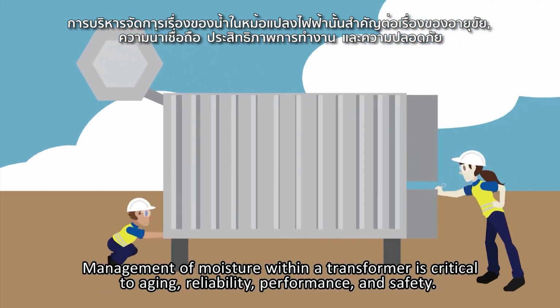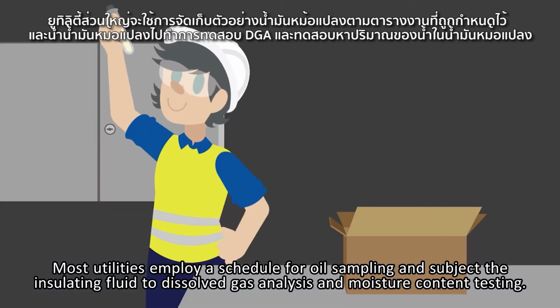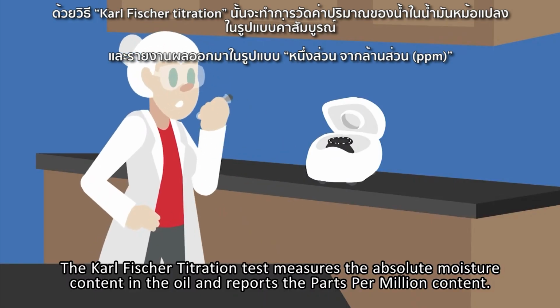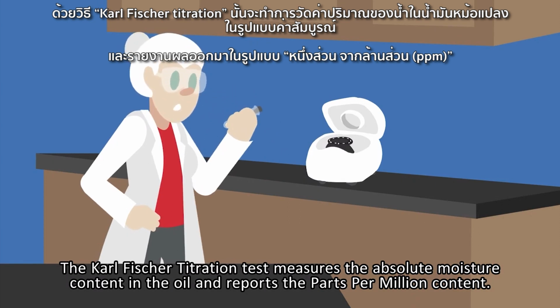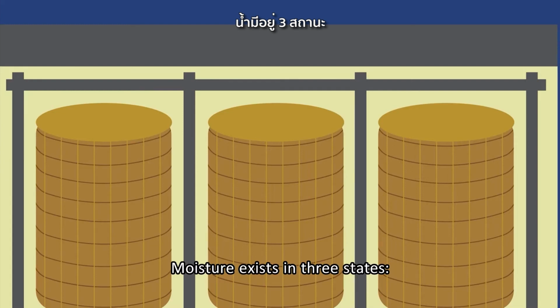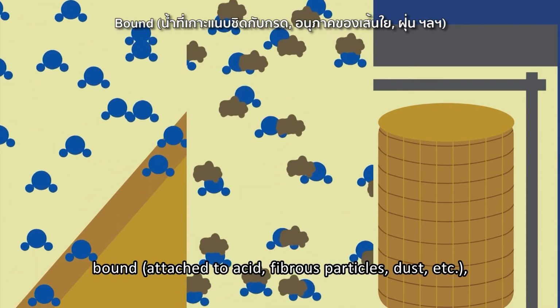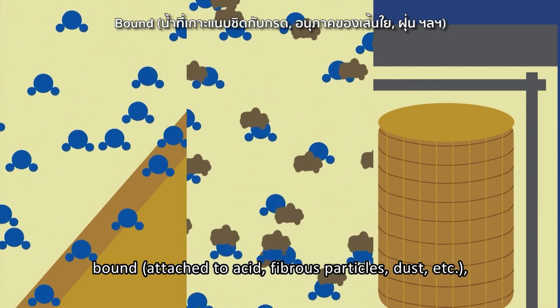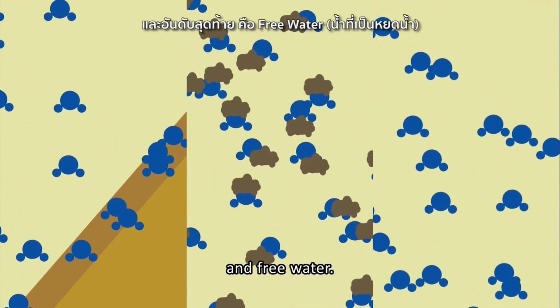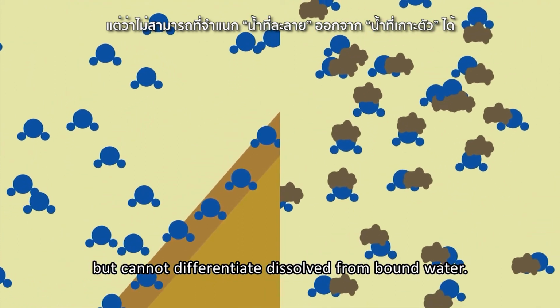Management of moisture within a transformer is critical to aging, reliability, performance, and safety. Most utilities employ a schedule for oil sampling and subject the insulating fluid to dissolved gas analysis and moisture content testing. The Karl Fischer titration test measures the absolute moisture content in the oil and reports the parts per million content. Moisture exists in three states: dissolved, free to move between oil and paper; bound, attached to acid, fibrous particles, dust, etc.; and free water. The Karl Fischer titration test measures all three but cannot differentiate dissolved from bound water.